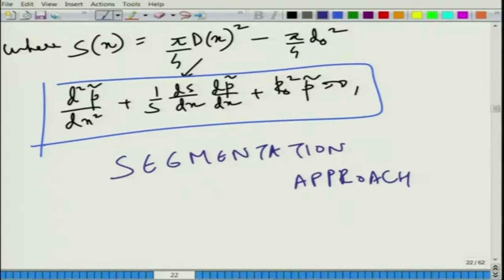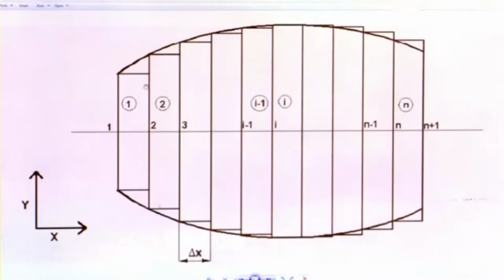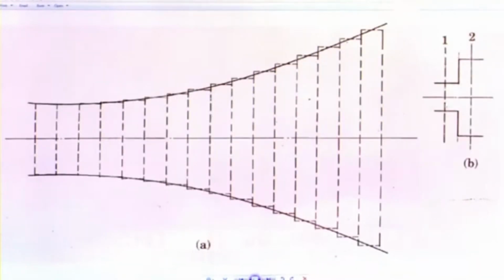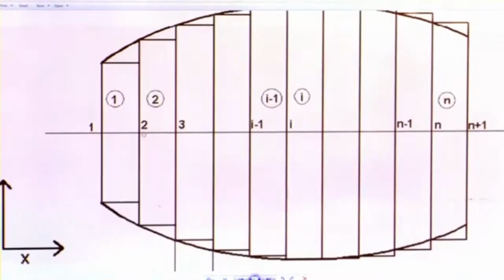So, what happens at the discontinuity? Let us look at this figure again. Let us focus on node 2. The node, or basically the plane at which we are looking at the state variables, acoustic pressure and velocity, is located in duct 1, but just at the interface.